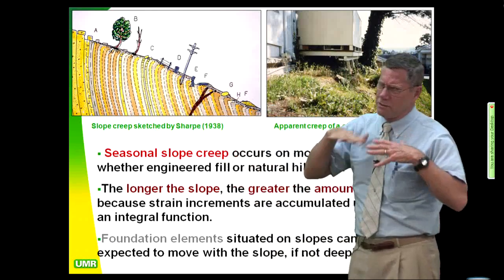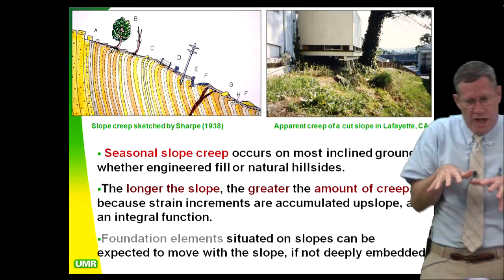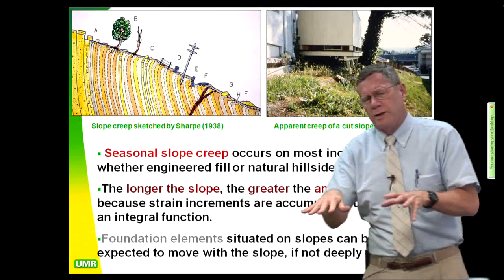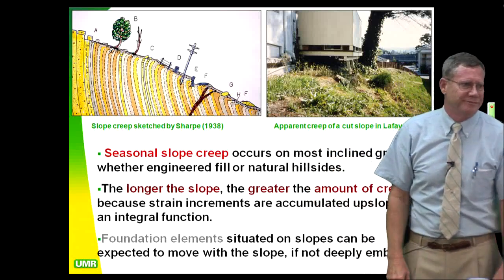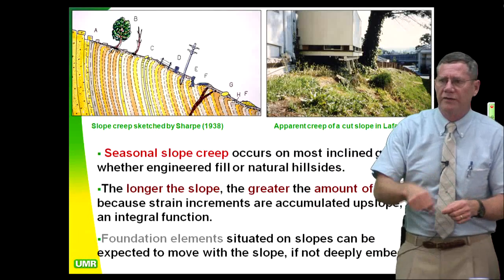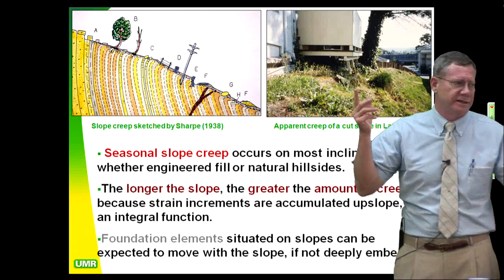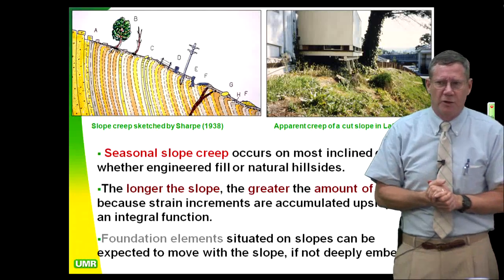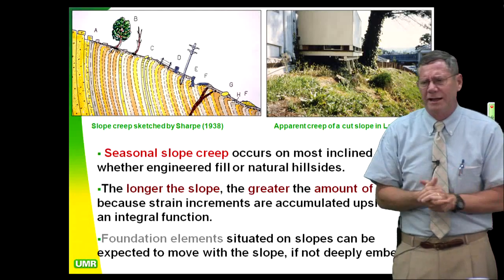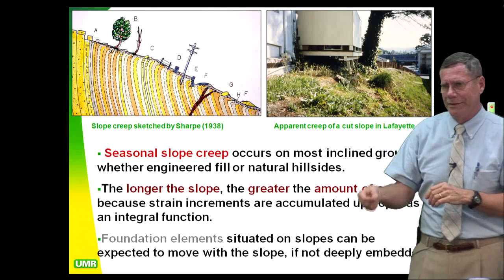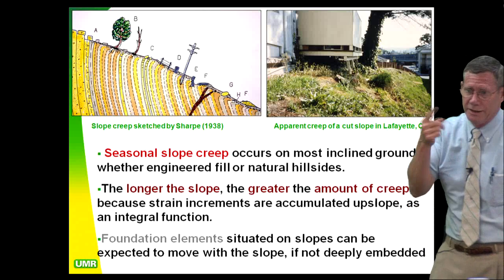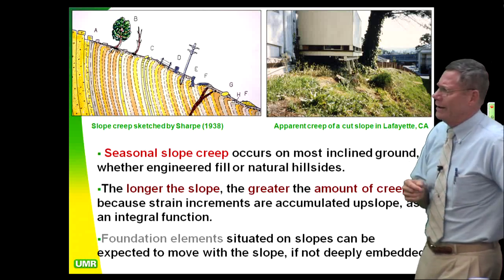They got lots of things creeping down the slopes. When I found the hot zones that were really creeping a lot, they were always broken pipes, corroded pipes, and they were just weeping. You know, they used sonic velocity testing. They didn't hear anything. Well, you don't have to hear anything to get a million gallons a year at one spot. That's just a little drip, drip, drip, drip. That's a million gallons a year. You can do the math on it yourself and figure it out.